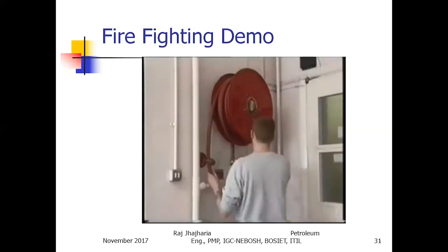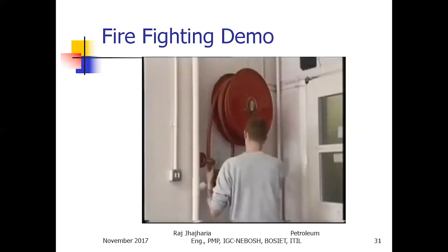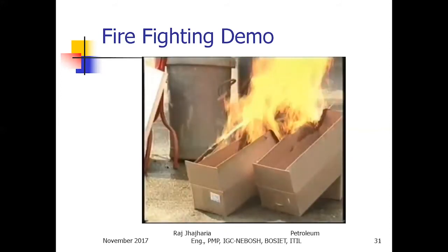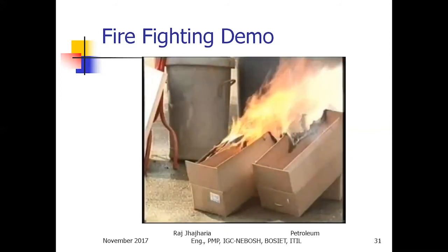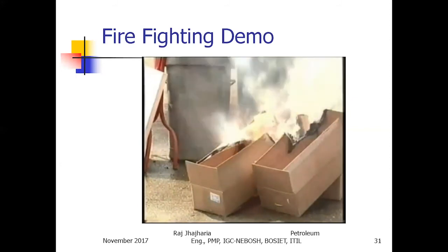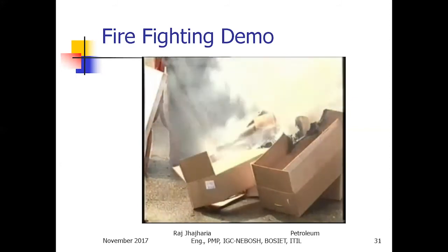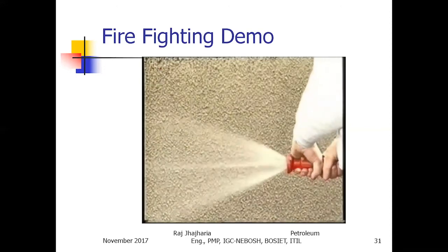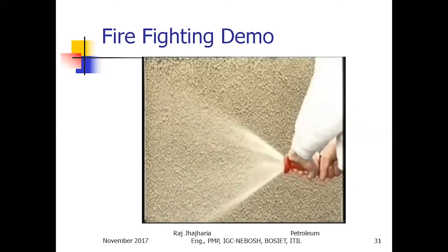An additional method of fighting fires with water is the hose reels, which are fitted in many buildings. Hose reels have some advantages over the water extinguisher. They provide you with an indefinite supply of water with greater pressure. When you open the nozzle, the water will come out as a jet. If you continue to turn the nozzle, the jet will turn into a spray.